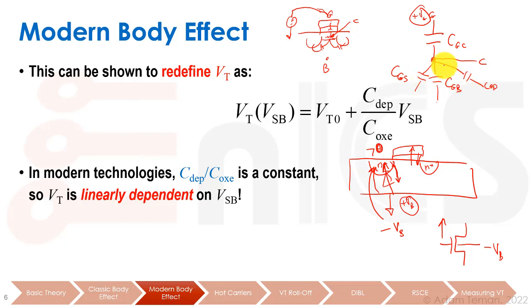So really, actually in FinFETs, that's kind of what we do. With FinFET transistors, we have our gate going over our fin, which is this. So here we have the current running over here. And now we have capacitances from all three sides, which is a lot more capacitance, and the capacitance of the body is only at the bottom. So we get much better control. We get the CGC getting much larger than the other parasitic capacitances, and that's what we want to do.